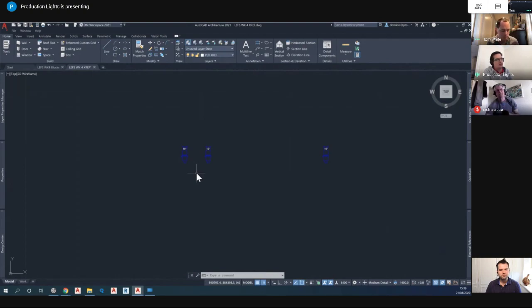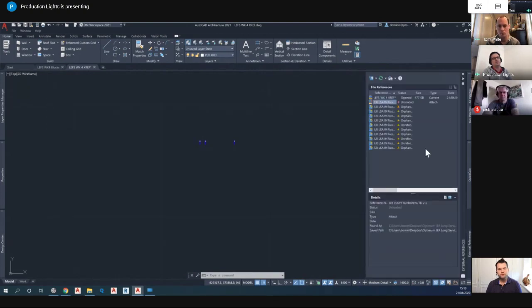And then any updates that were going on, Tom could either send me a new drawing and I could update it with my reference, or he could take them into his drawing. So hopefully that describes it a little bit better. Wonderful. And that was the unload one we talked about before. I hadn't shown it before, but if you want to put it back in again, if you have to put it on the layer itself, then just hit reload, and it'll just bring the reference back in again.